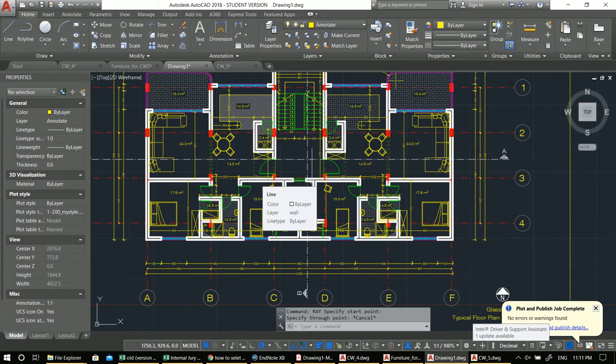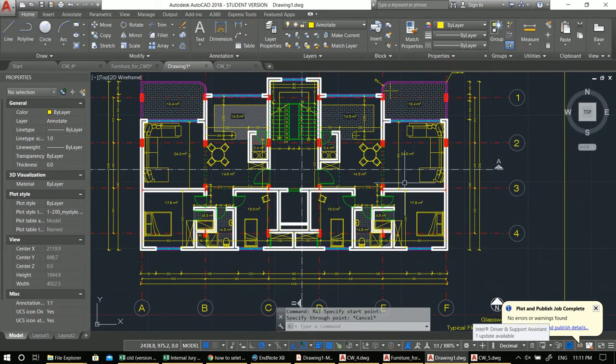I mean, back in the day, we used to draw all sections in AutoCAD, but nowadays I'm advising them to go and learn other more productive software like Revit, which updates the section if you apply some changes. For technical drawing, at the end of the day, you can bring it into AutoCAD. But AutoCAD these days is just for making sure that everything is in place, for defining better line thicknesses, and just to prepare the printouts. Although Revit is getting there more and more, better and better every day.